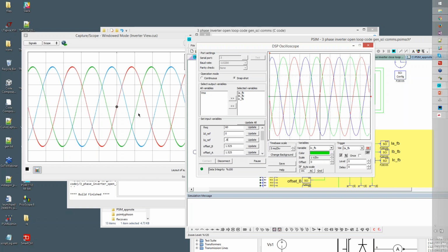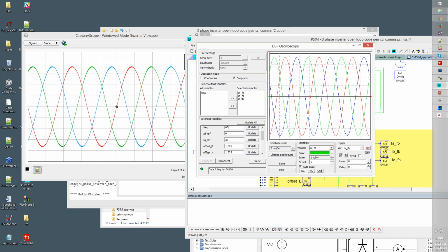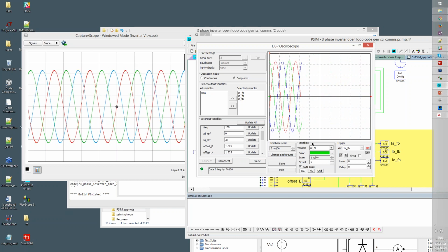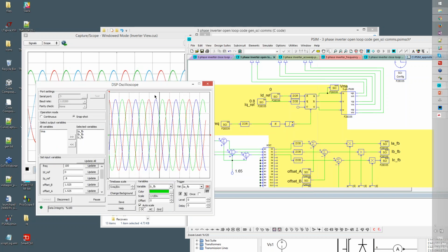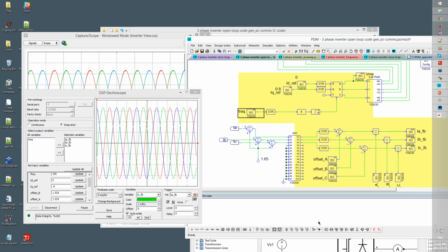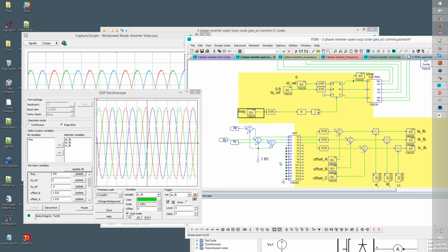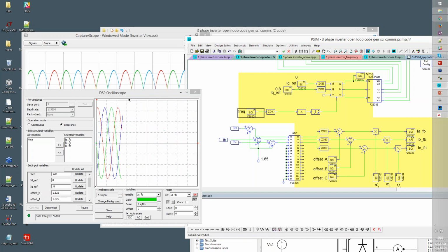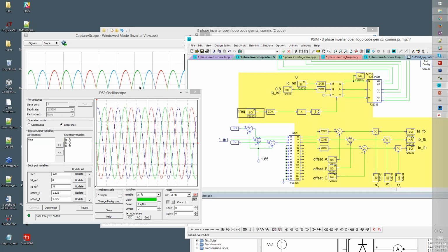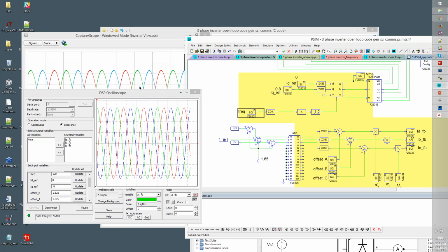Yeah, we can see on the left-hand side all these signals are bouncing around. I can also have access to the frequency. So there's 10 hertz, and then there's 100 hertz. So I can change these numbers on the fly as well. These are all numbers that are accessed over the serial communication interface. So it makes it really easy for me to check things and confirm things and play with things during runtime instead of pre-compiling all the time.